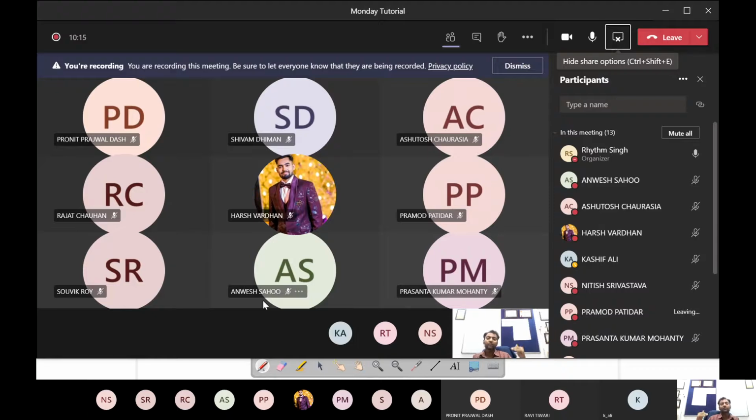But it is always recommended to have some, because load can fluctuate on either side. Ideally, you should always have some dummy load in place, because if the load increases, you can throw off some of the initial dummy load and still account for the frequency change. So better control will be there if you always have some dummy load in place.